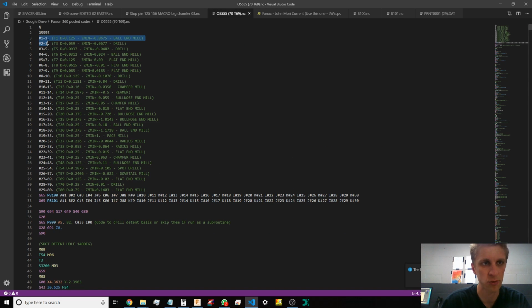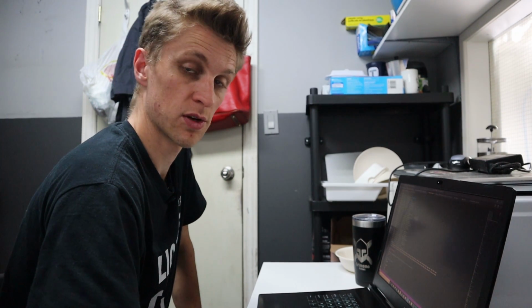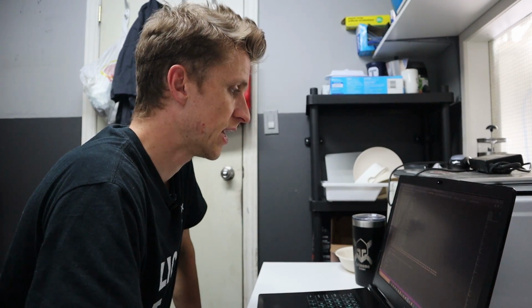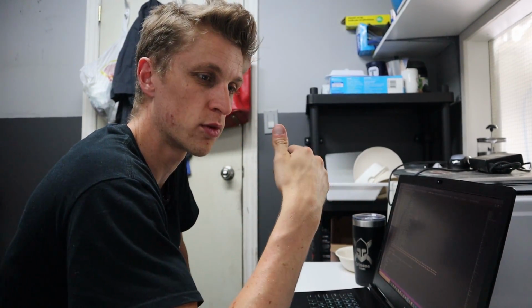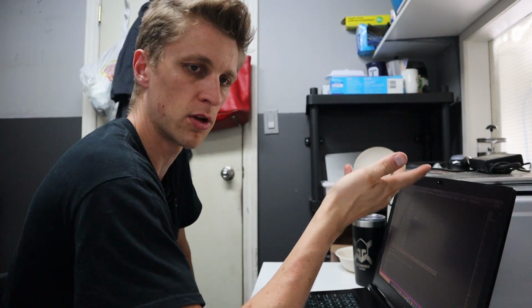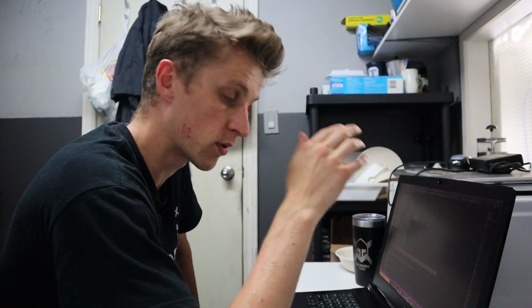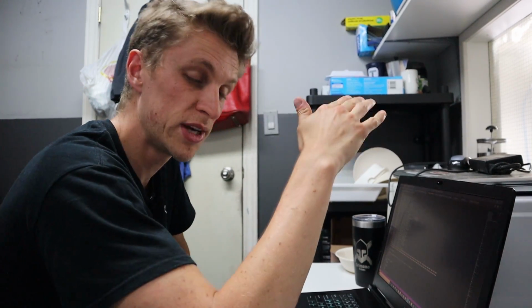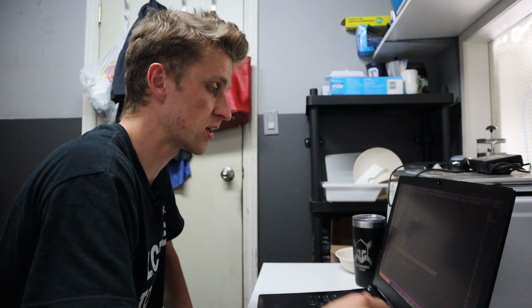So this lets the macros know that I've got tool 1, tool 3, tool 5, tool 6, tool 7, tool 9. Because what would happen before is if we didn't have the last tool, say we didn't have tool 80 installed in the machine, for whatever reason, we pulled it out, needed something else, it would machine the entire pallet until it got to tool 80, and then it would say, hey, where's tool 80? And then it would just hang up an alarm there overnight, all day, whatever. So I needed a way to pre-check to make sure that all the tools are in the machine.